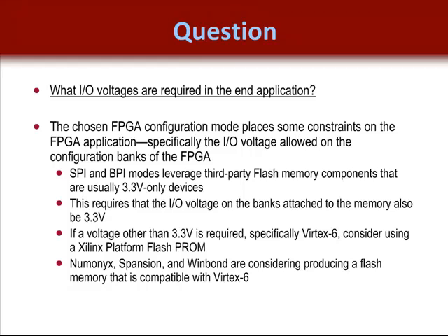In this case, it is important that the designer be aware that the FPGA configuration pins are reserved and usually placed in a single I/O bank. Thus, depending on your configuration mode, that will require all the I/O pins in that bank to be compatible with a 3.3 volt device and may limit where you want to place your other I/O pins on your FPGA. So, plan your use of the bank pins associated with your dedicated configuration pins a little carefully.